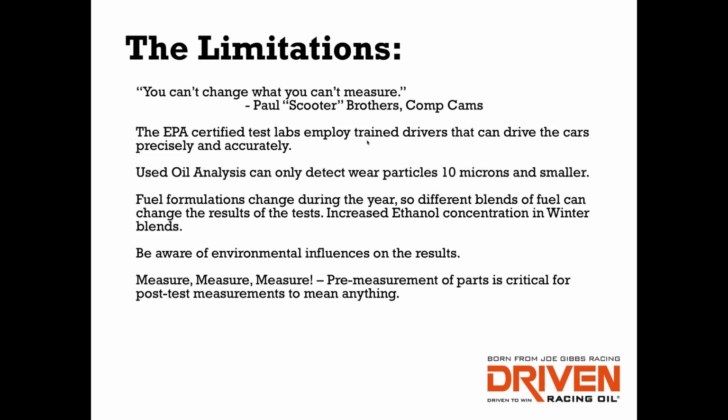I talked about used oil analysis and how beneficial it is in terms of being able to see inside your engine. One limitation of used oil analysis is that it can only see particles that are less than 10 microns. So if you can see a bunch of stuff in the oil, it's already so bad that the used oil analysis can't see those particles.